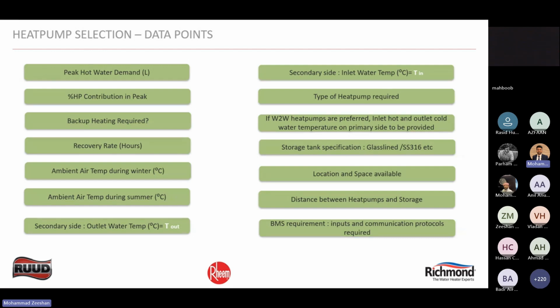Now, there are some data points that we normally ask when we do the sizing and selection, starting with the peak hot water demand. This is something we always ask our customers, our consultants, and all our mechanical engineers. A lot of different consultants follow different building codes. I have used ASHRAE as a base for our calculations today, but if you would like to follow any other standards, we can do that as well, based on the comfort the consultant has with those codes.